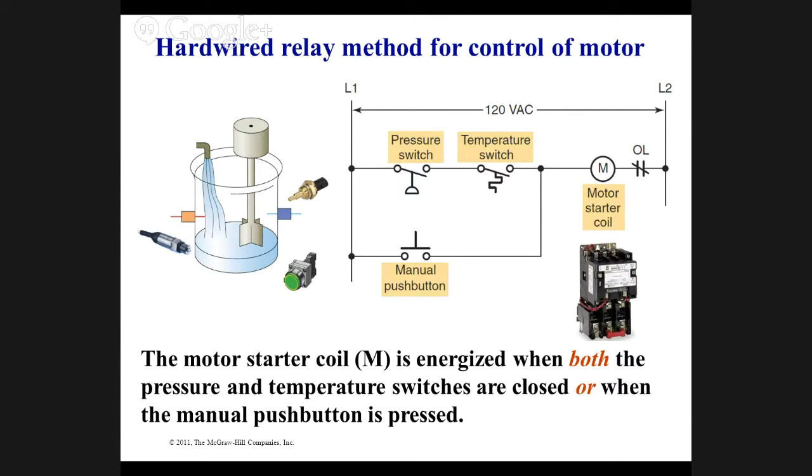Okay? And the motor is going to agitate this tank like a washing machine, right? Alternatively, we can hit the manual push button and we will bypass. You see how electricity would flow through here, here, and then turn on this? We can bypass that by turning on this manual push button, going around, and then going to the motor. Does that make sense?